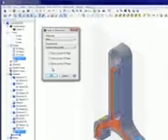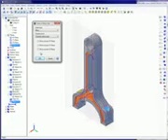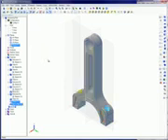In this dialog box, mirroring is a global feature and often used to create right-hand or left-hand versions of the same part. Three of the features are colored to make the transformations easier to see. This is a mirror across the XY plane, with the transformation about the origin. Notice how the orange feature swaps sides, but the yellow and blue holes stay the same.